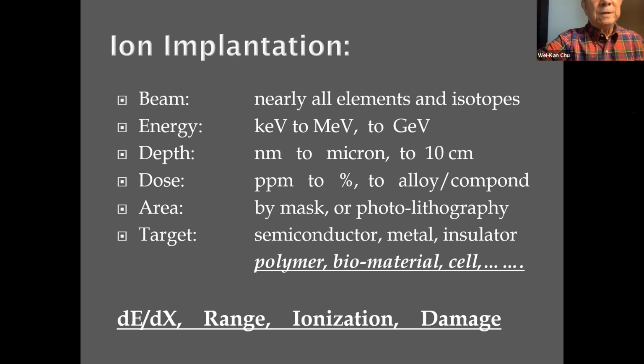This window is pretty large, let's just say a micron by micron window. Therefore the phosphorus distribution in this window we first say is pretty uniform, but still there could be some areas with more phosphorus, some areas with less phosphorus. The distribution is a Poisson distribution.